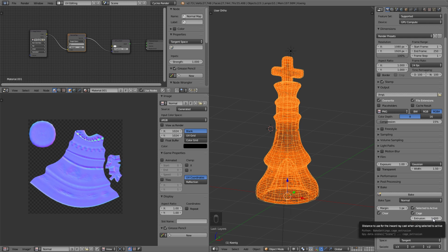Well, when you do it like this, then Blender will create a virtual object from the object you have now, and the virtual object is exactly like your object but inflated, scaled along the normals. It will be used to serve as a direction of the projection. This will actually help you when you have these pieces around the crown of the king, because once they go up and once they go down, and by setting the direction correctly, the cage object will help you with this problem. So just try it and see for yourself. It will work out really fine.